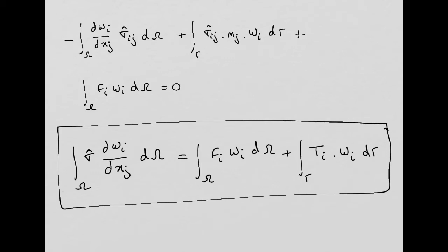The third step was to multiply the residual by a weighting function and integrate it over the domain of our problem and make all of that equal to 0. Then the fourth step was just using the Green theorem to obtain this final equation that you see here on screen, okay? And now the most interesting and important stuff for finite element analysis is coming, and it's quite important what I'm going to do from this point, okay?